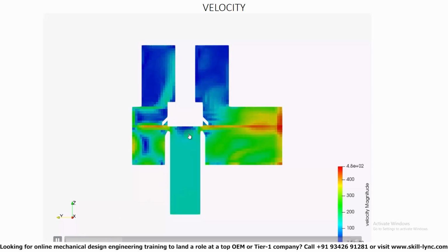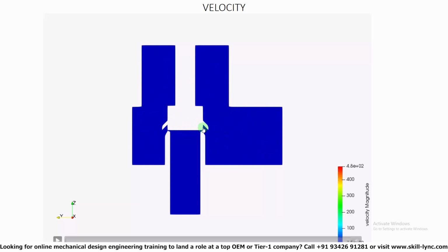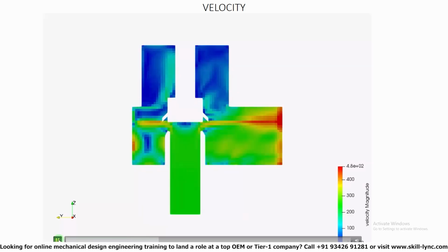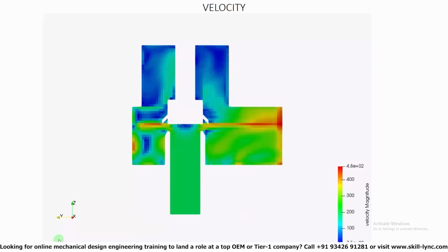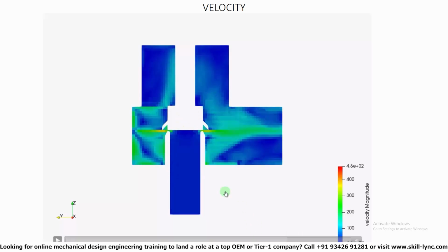You can see that initially there is a lot of movement in the valve, but as the inlet pressure is slowly dropping, you can basically see that all the action dies down. Now the important assumption that I was talking about, I'll show it to you, and I'll pause the video in the right location. At this point, if I just move up, you can see that the inlet pressure is restored to its baseline value, but you can see that the flow is still taking place. In other words, this particular computational model lacks a very, very important concept, which is pressure buildup.